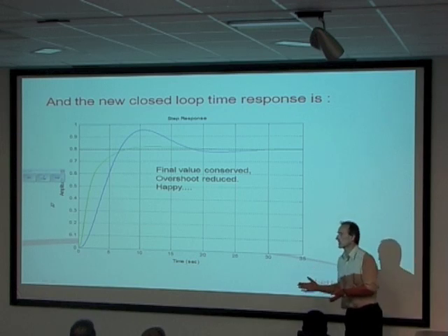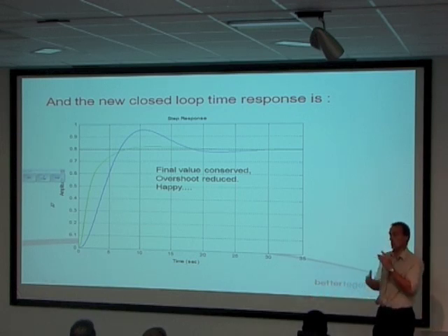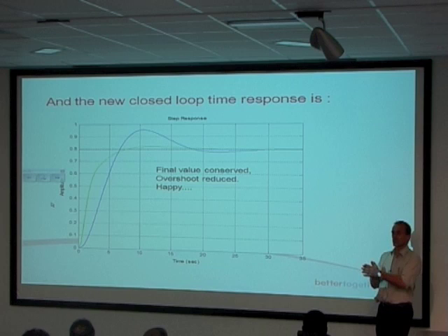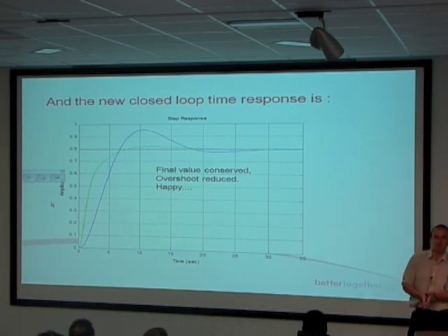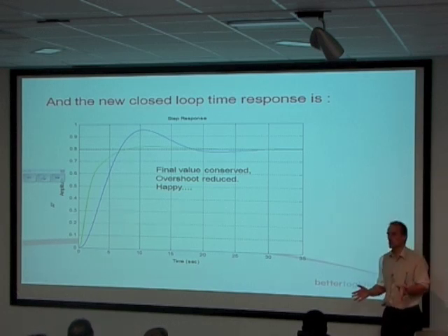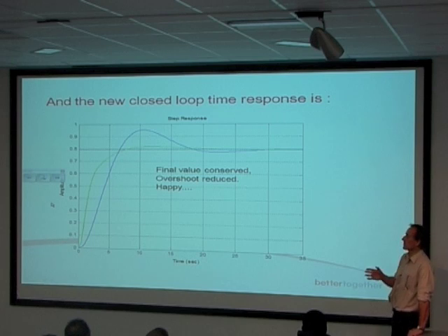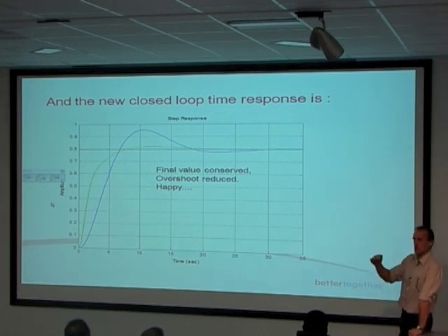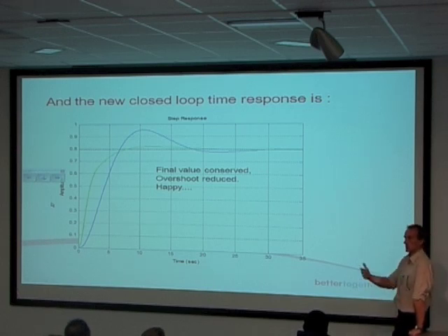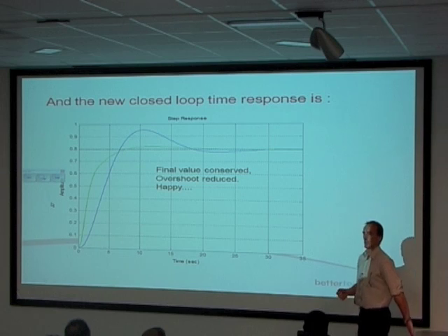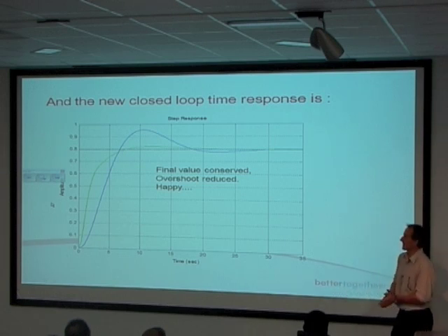If it's got some kind of equipment on board where it's important that it's pointing in the right direction, which could be a camera or something like that, it's the settling time that matters. It's the time at which we can say, yes, that's pointing in near enough the right direction, plus or minus 5%, we can now take the picture. Or it could be something more offensive, like a weapon. I don't think that device is.